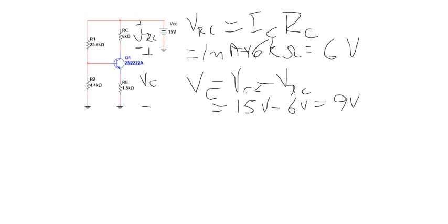And we can find the VCE. We define that on a voltage convention as being VC minus VE. Again, that's a Kirchhoff's voltage law thing, actually, but we've already defined it that way. Anytime I have two subscripts that are different on a voltage like this, that's a point-to-point voltage.